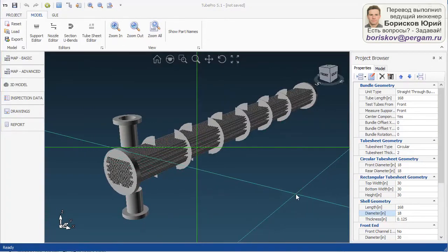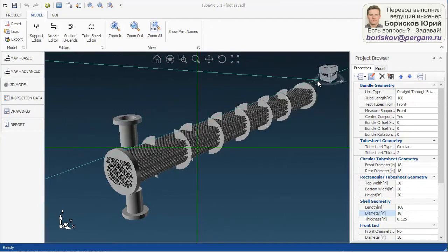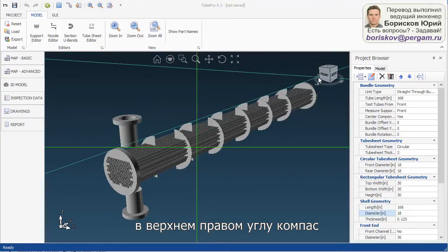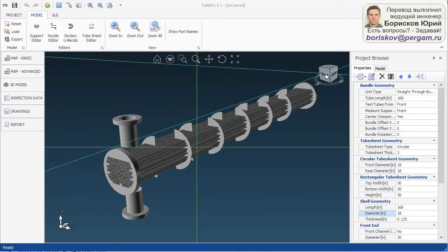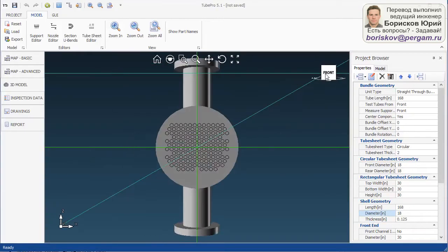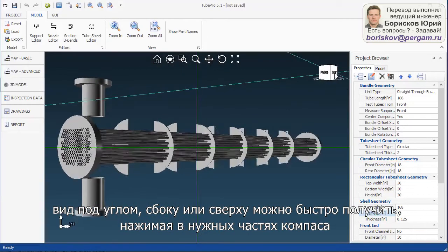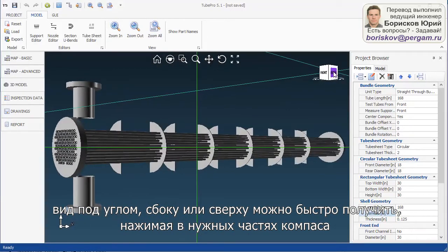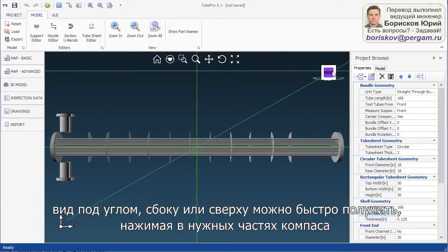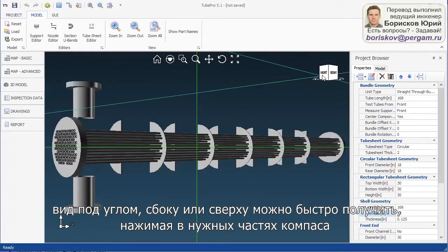Another cool trick that is available to align the model is to use this top right corner tool here. By clicking on this, you can decide to have a direct orientation, like from the front. If you click on the edge, it's going to show it at 45 degrees. I can click right. I can click the top edge, so it's going to move it this way. And I can quickly do that.